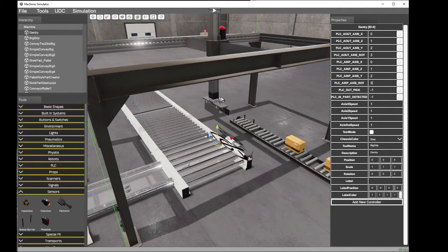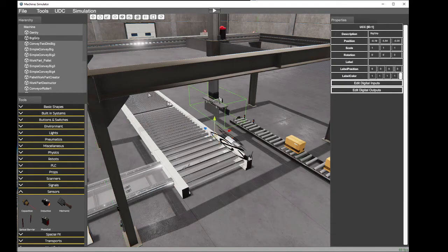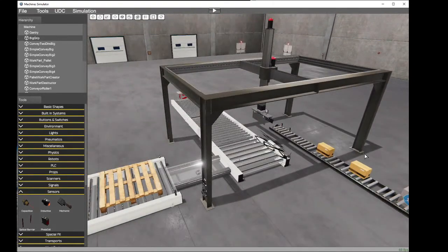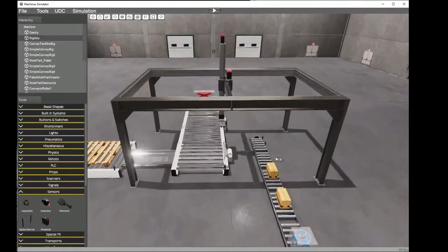And the input to make the tool aspiration we are not going to use, because we are going to use the ones for the grip we have created. Okay, for the grip, let's program the I/O. We select the inputs. I'm going to write for the digital inputs for the detects 1, 0, 1, and 2 for the open grip. And the outputs, the 0 for take box 1, 1 for the 2, and 2 for open the grip. Okay. Now we have all ready to be programmed by the PLC.